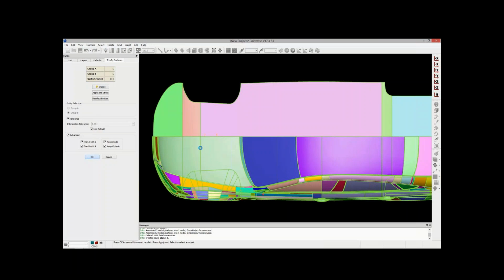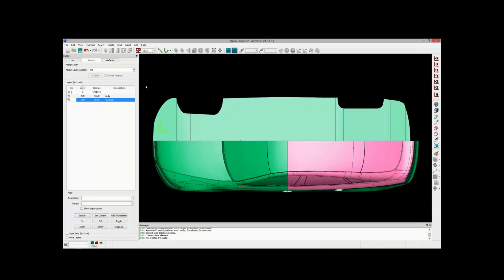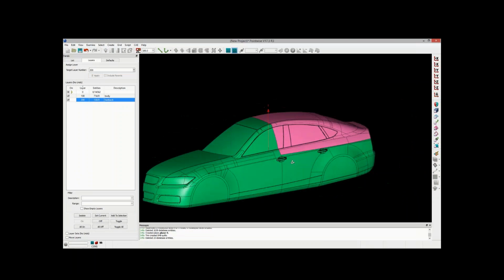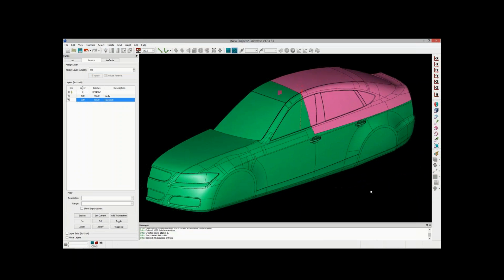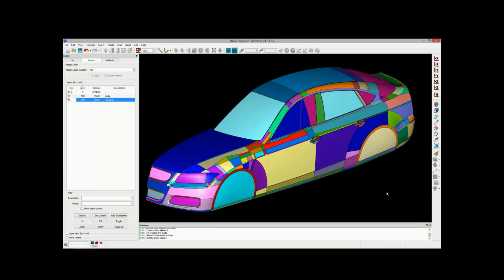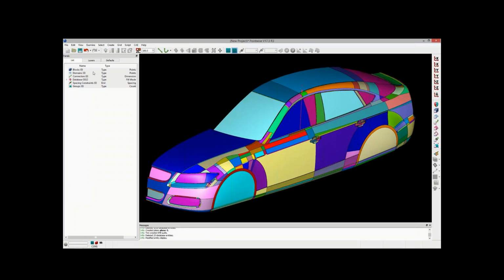Okay, and I don't know that there may be other lamina boundaries in other places in the model, and because there are so many on that symmetry plane, it makes it hard to identify where others might be without exiting that panel. So that's why I did it for the whole car. Then I cut it in half because I only want to have to do half the work. I only want to create quilts for half of it. I only want to mesh half of it. And when I'm done, I can just mirror the result.